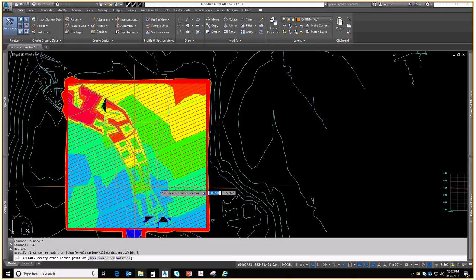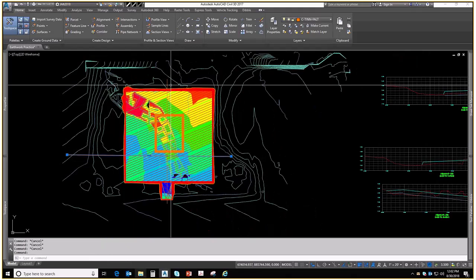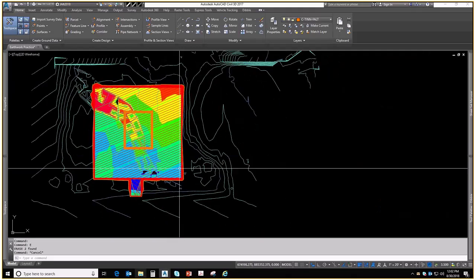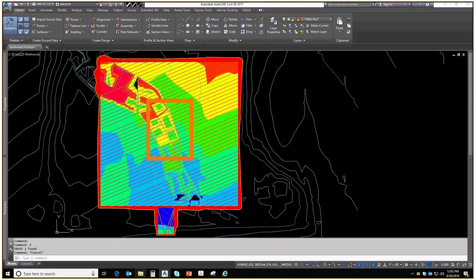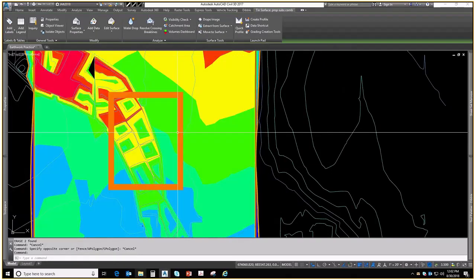Yeah, and I think the first 2 areas are just methods where Civil 3D can compare vertical surfaces and generate the volume between them. When we're working with cross-sections, it's the more traditional method, and the value of using the cross-section method is it's much easier to check the work that Civil 3D is doing.